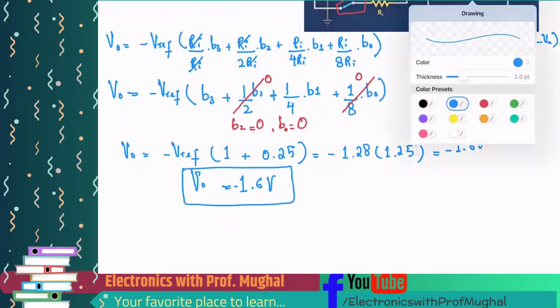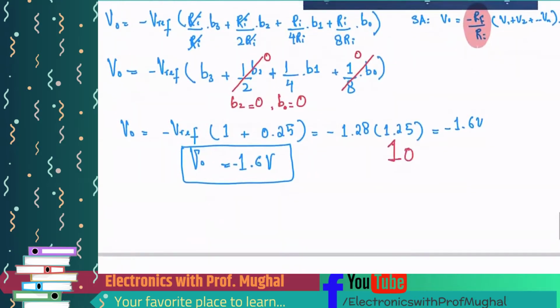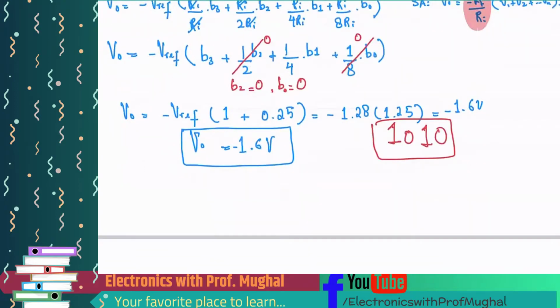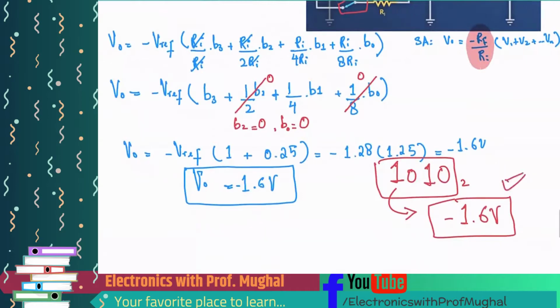What does that really mean? Well, it means at the output, when we are getting data which is 1010, as it was, a digital signal in binary, it is equivalent to saying negative 1.6 volts in the analog world. And now again we can convert this negative 1.6 volts into some audio signal. And that's what this DAC is doing. It's converting the digital number back into audio.